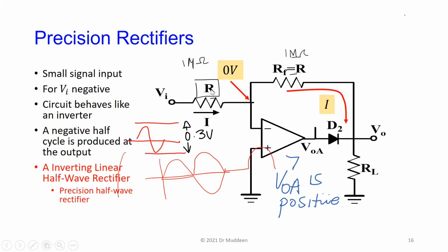Beyond that, the current flow in these circuits starts to get close to what the amplifier takes. Although we say it doesn't take any current, the real commercial amplifiers take a very few microamps, right? The better ones take a couple of nanoamps. The really, really good ones take picoamps.